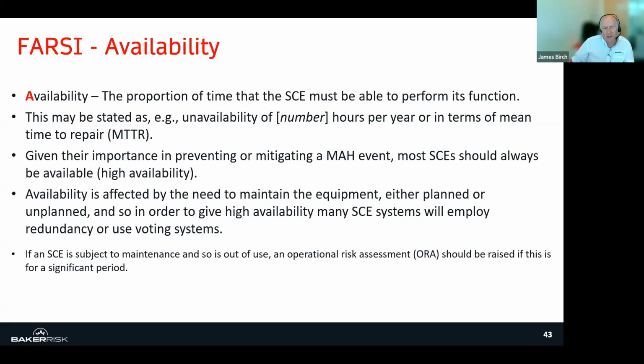So I've then got to consider, how do I deliver that? Can I trust just by having one emergency light? No, I'm probably going to need several. So in order to make sure I have that availability, because perhaps I need to take some of them out for maintenance, I'm going to have a minimum number in each area.